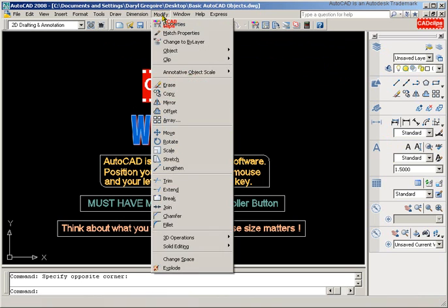Okay, we have our modify tools, erase, copy, mirror, extend, offset. Okay, notice you can type in a Y or an E or an R, the underlined letters on here, meaning if you get this far and you just type in an F, it will be fillet. You'll get that command. Okay, again, erase, fillet, copy.